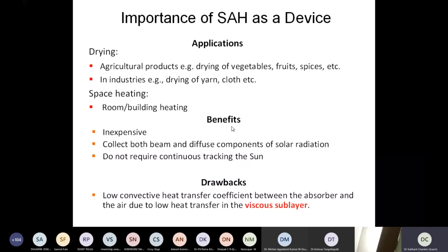When you talk about applications like the solar air heater, generally the Reynolds number is of the order of 10,000 to 20,000, right? Depending upon whatever duct size you are using. So for those types of application, the flow is turbulent and a viscous sublayer will be formed, which, as I said, impedes the heat transfer, and that is to be seen more carefully, right? This is some basics, right?